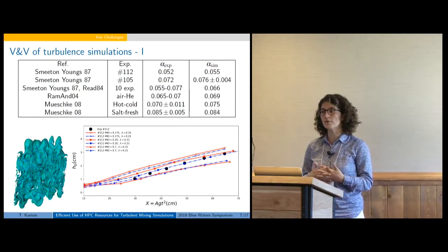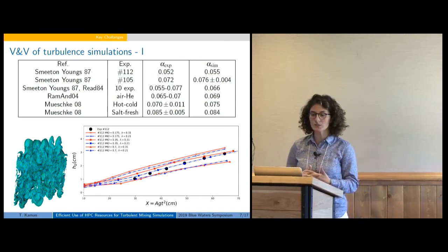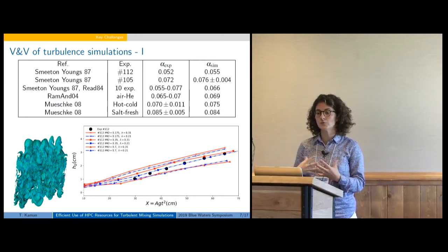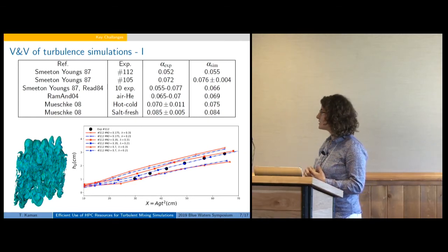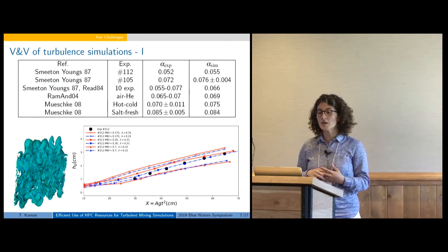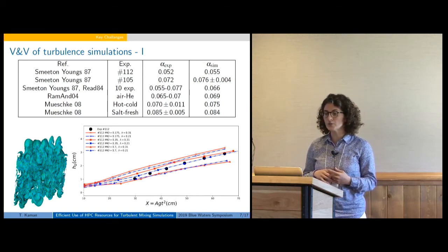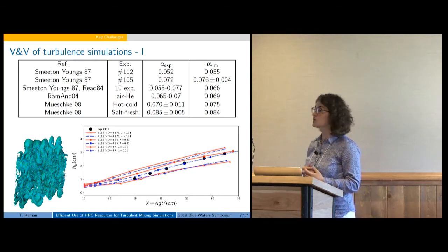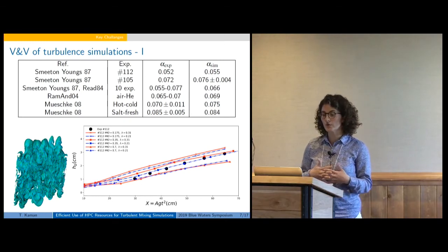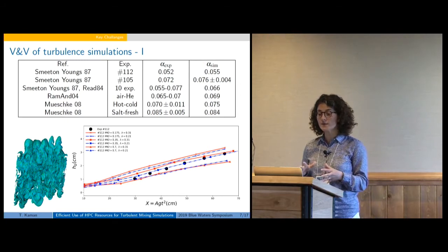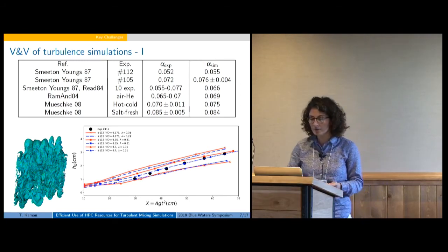Initial mass diffusion coefficient, long wavelength initial perturbations, and so on. On the left-hand side, the green, you see the late time fluid mixing. And on the right-hand side, we have the black dots, which are the experimental data points coming from Smith and Young's '87 report. And we actually achieve a good result with certain parameters where the initial mass diffusion is 0.35 and the long wavelength, the most unstable wavelength, is 0.21.